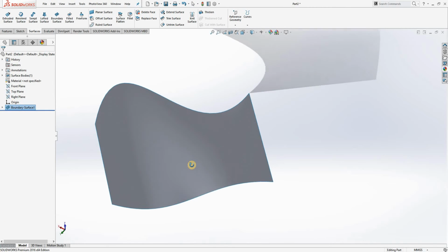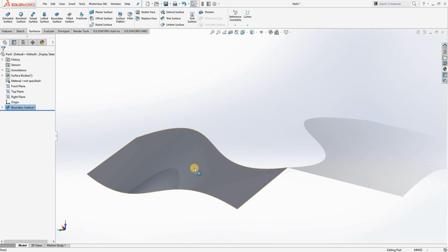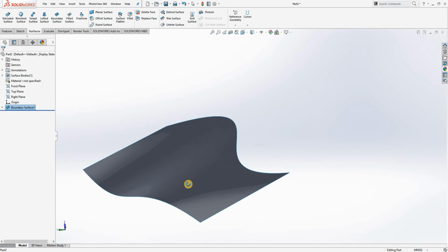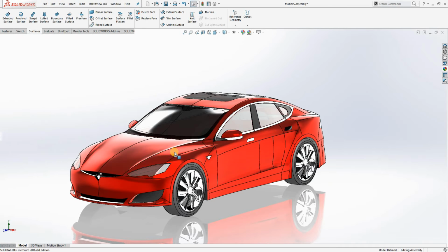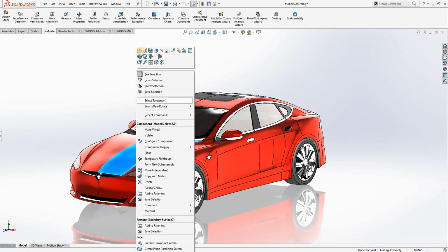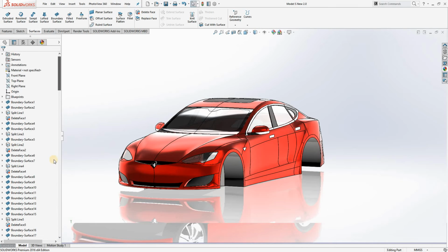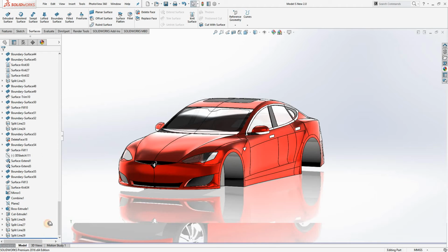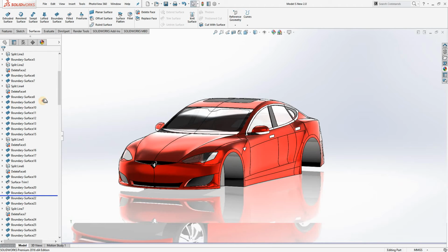Generally speaking in SolidWorks, when you're creating a surface, you want to have 4 bounding edges. The underlying mathematics prefers that, but there are some ways around that, and I'll go into more detail in the video. So jumping straight into this, I'll open up the main body. As you can see, there are quite a lot of features in this model. I'm just going to quickly go through. It would take far too long to go over every step.